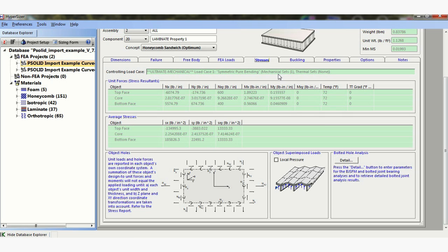I want to see strain 1, strain 2, and strain 3, and I want to see the allowables in each of the 3 directions. I'm using max strain theory, the margin simply, the allowable strain in that direction. I'll get this the right way. Yeah, the allowable over the applied, minus 1. So, you know, that's good.